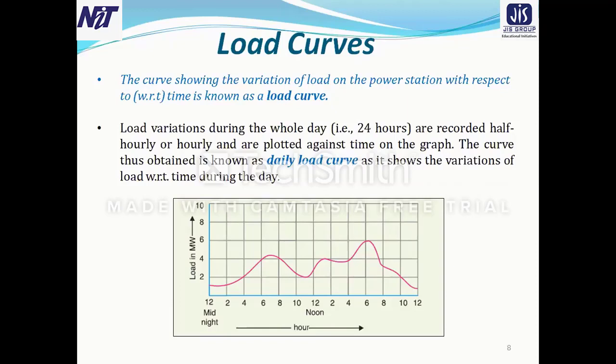So we can represent the load demand like this, and this is basically the daily load curve. Load variations during the whole day, that means the 24 hours, are recorded half hourly or hourly and are plotted against time on the graph. The curve thus obtained is known as the daily load curve, as it shows the variation of the load with respect to time during the day.